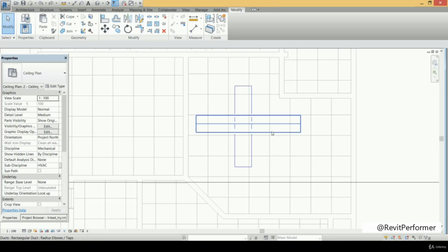And this is to allow the airflow through the reducer to go as easily as possible and not to have any disturbance inside the reduced height duct or inside the duct reducer. And finally, the last condition and the most important one is that the height of the reduced duct mustn't be less than 80% of the old height. Or in other words, the reduced height mustn't exceed 20% of the old height. Now let's see how to perform those concepts practically.